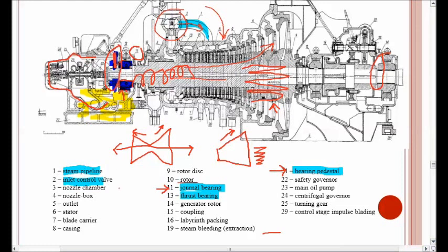The thrust bearing commonly used is a Kingsbury type thrust bearing, which we can look up on the net for more information. So to conclude about the bearing types: first we have a pedestal, a static thing, on which a general bearing sits, and the thrust bearing is the one used to avoid axial friction between the rotor and the stator. Now we move on towards the generator rotor.